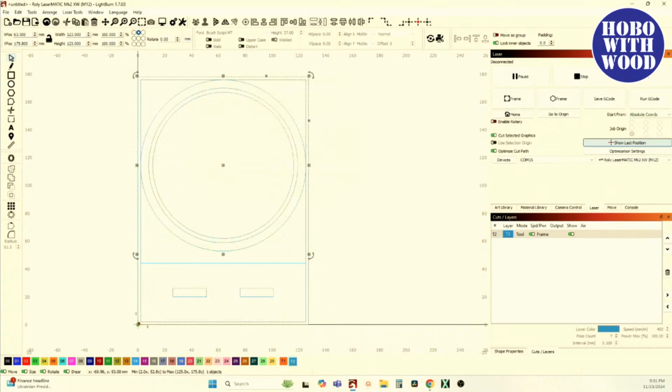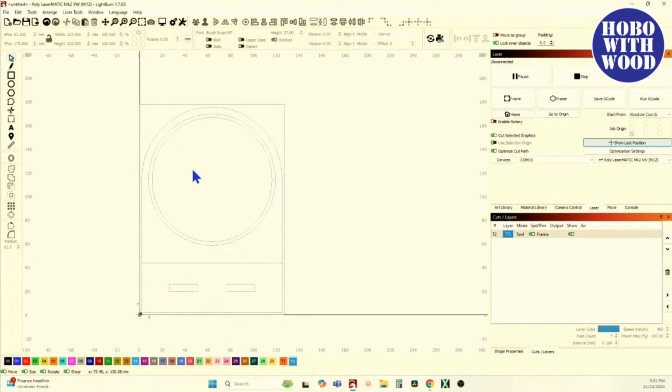So I can say okay, and there it is, I've already got it at 61.5. So I'm just going to come up here and put a radius there and there. Then I can select just that circle that I created initially and delete it. And that quick, I have the pattern for that design.